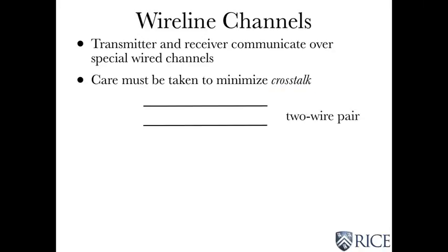So let me take a simple example, which is known as the two-wire pair. You need two wires because let's assume a sending station is a voltage source, and you can't apply a voltage except if you have two places to apply that voltage. That's why you have a two-wire pair. And let's assume the receiving system looks like a simple load resistor, for example.